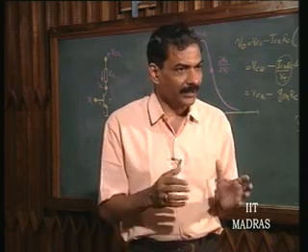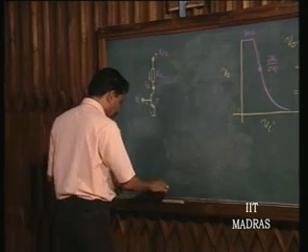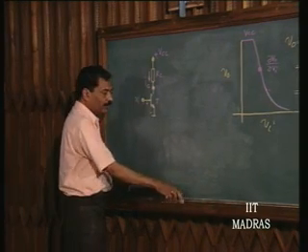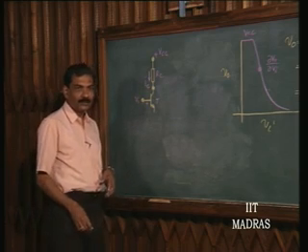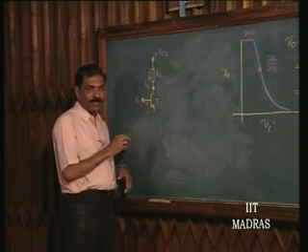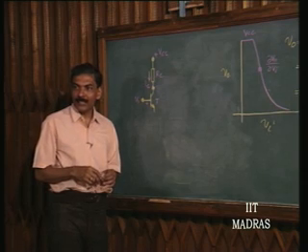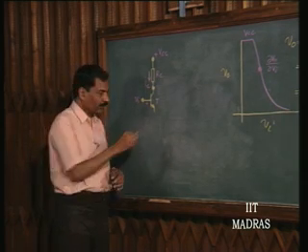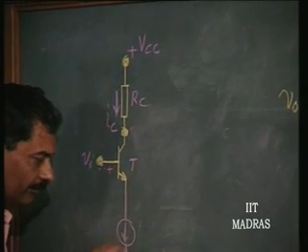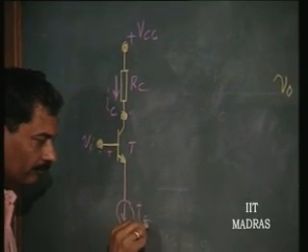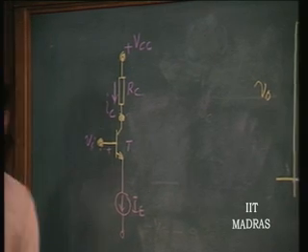They take up a lot of area, and therefore, this concept of biasing it by means of another supply: how do I bias it? Now, I can put a negative supply, but I just told you that it is easier to supply a current into it and force the voltage. So, I would rather apply here a current, using a current source.